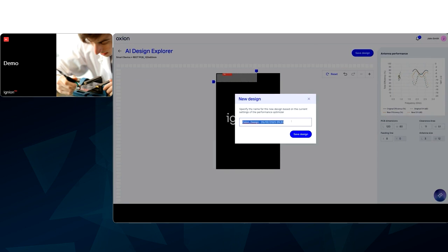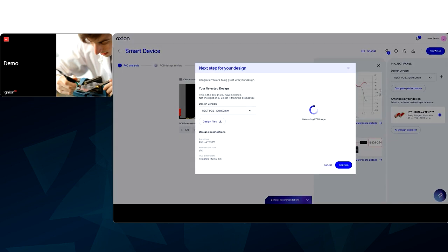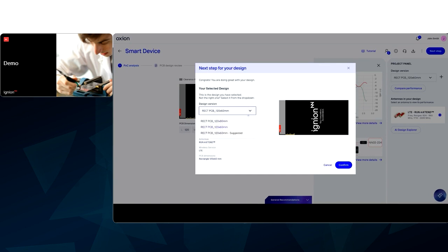It's also covering 1700 to 2690 megahertz in frequency. And we're using this AI design tool to work out the prescribed antenna location, clearance area, feed line routing, and to optimize the design to see what yields the best efficiency and bandwidth match.